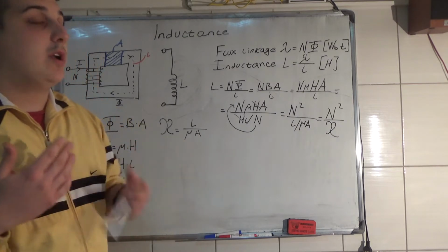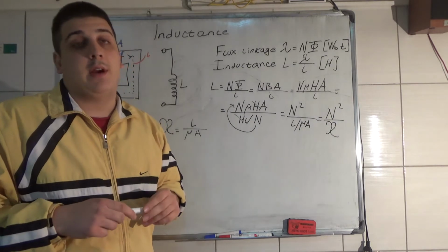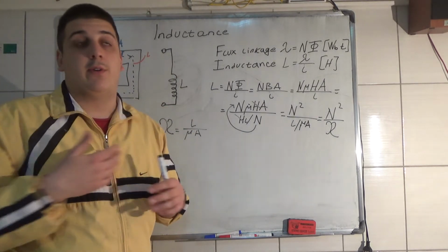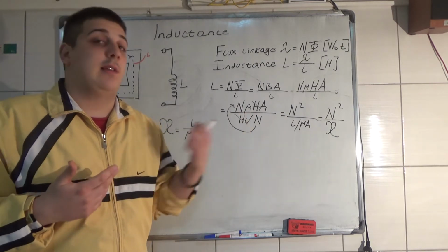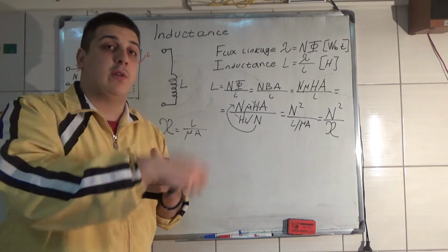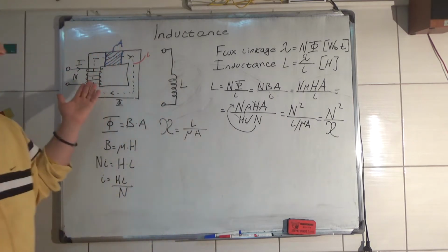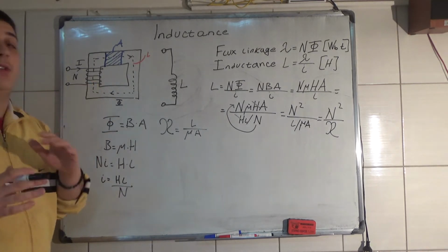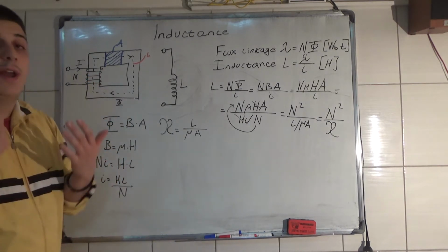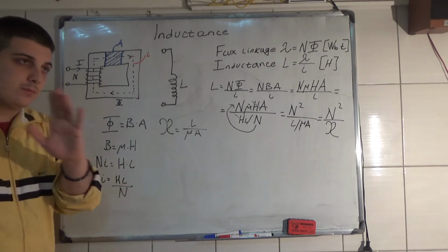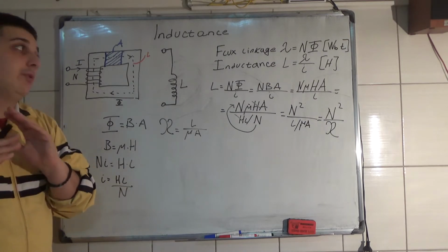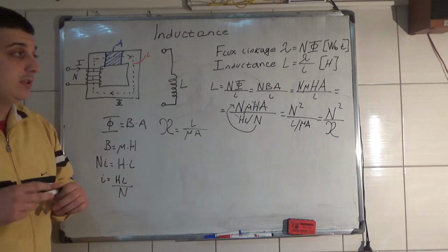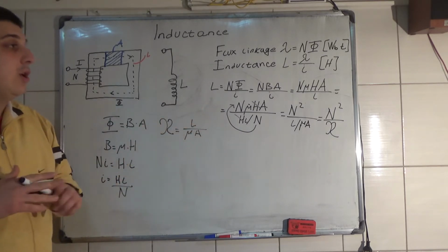So you always have to watch out with these formulas. There are pros and cons, because you can make the number of turns, theoretically, go to infinity, but the more turns, the longer the conductors of this magnetic circuit, so the electric resistance of this coil is going to be higher. And you have to put in more active energy to magnetize the magnetic circuit. But that's not important now. In these lectures you will see this in transformers, synchronous machines, DC machines, induction machines, and you will see how important this is. So these are the formulas.